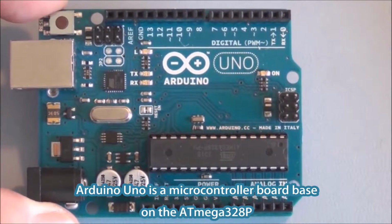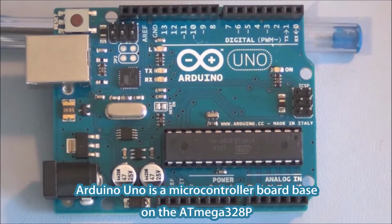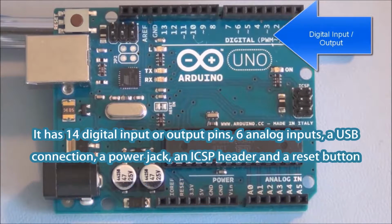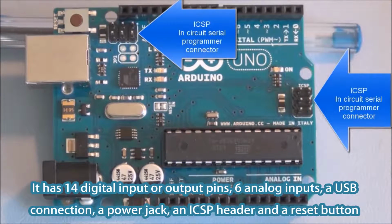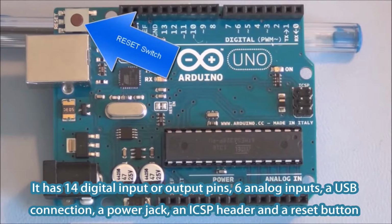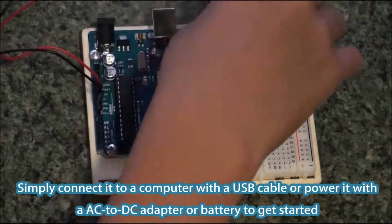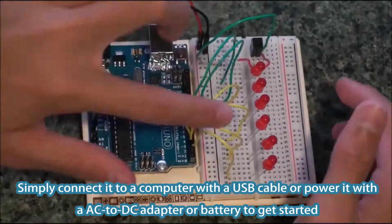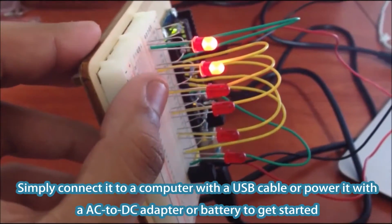Arduino Uno is a microcontroller board based on the ATmega328P. It has 14 digital input-output pins, 6 analog inputs, a USB connection, a power jack, an ICSP header, and a reset button. It contains everything needed to support the microcontroller. Simply connect it to a computer with a USB cable or power it with an AC to DC adapter or battery to get started.